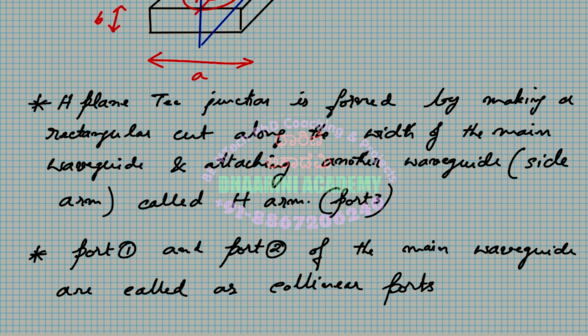All right. So the next part is, why do you call this an H plane T? There is a specific reason behind that. The reason is the axis of the side arm is parallel to the planes of the main transmission line. All three arms lie in a plane of the magnetic field, so the magnetic field divides itself into the arms.